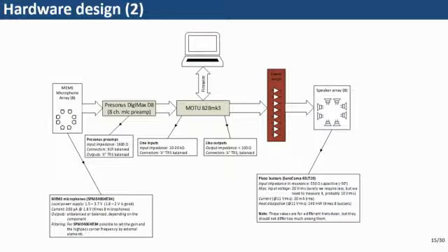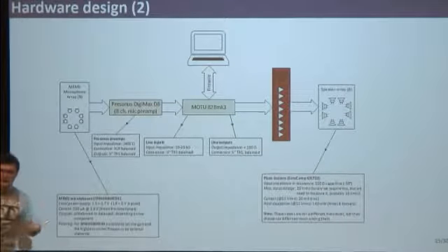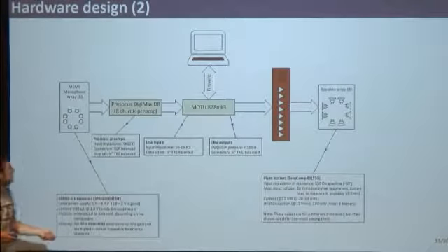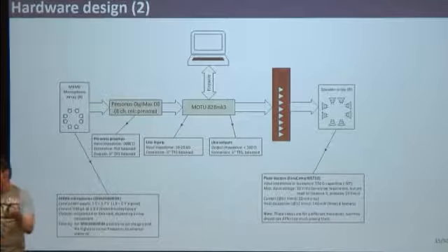We have here the microphone array and the speaker array. Microphones go to microphone preamps and then to the Motu unit, and everything is driven by MATLAB from a PC using FireWire, actually USB. A cool thing is that you could actually drive these directly to the Motu. This is something that we learned later, but the preamps are just in case we wanted to preamplify them a bit.